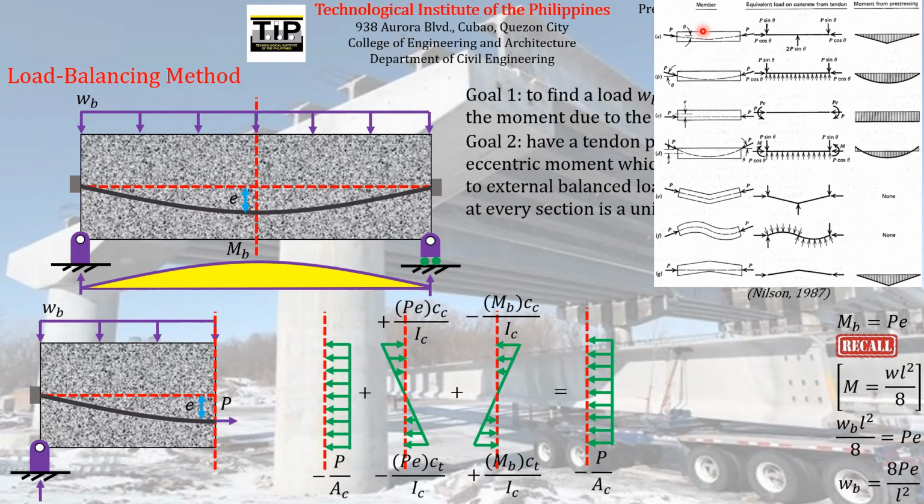Say for example again, if we have a concentrated load, we know that the moment diagram for a concentrated load applied downward at midspan on a simply supported beam will look similar to this, but in the opposite direction. It must be positive.